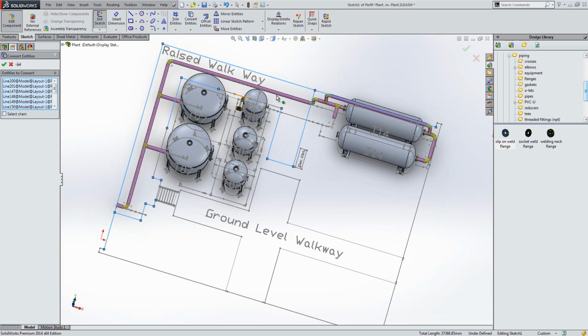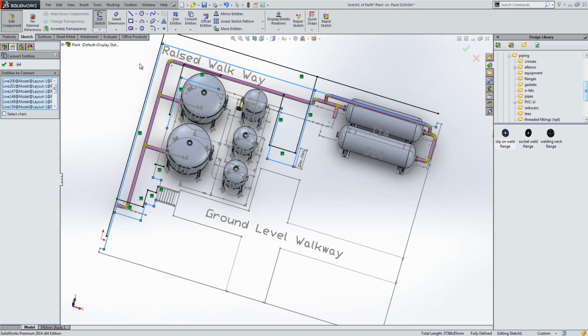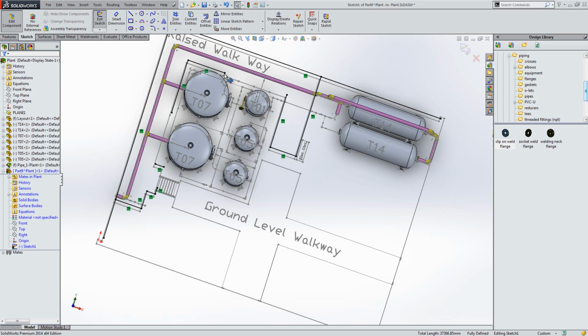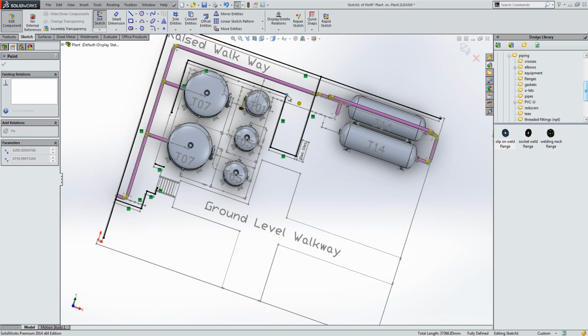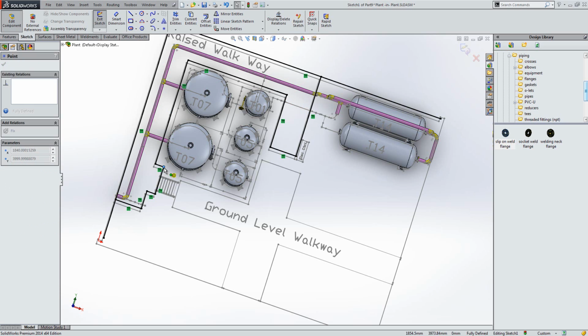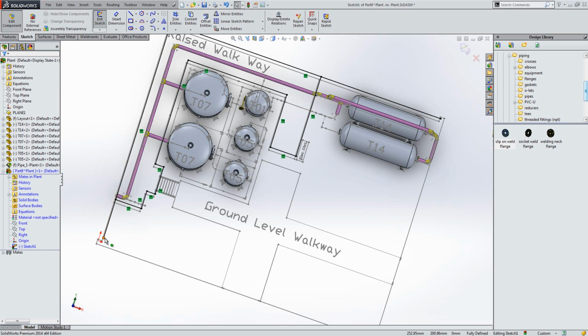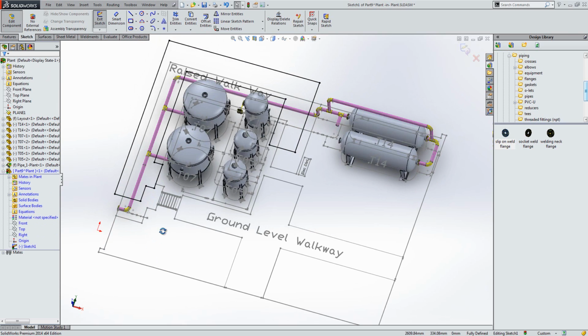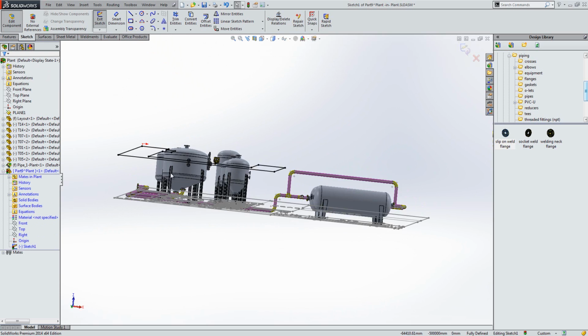You may notice that I've left some gaps. In this case, it's because what I'm going to do is extend the lines that I did select and just join them up. And this means that I end up with single line segments, which makes life a lot easier when we come to look at putting weldments and things along it. I also need to drag back the overextended lines. I could equally use the trim command. So that's my sketch for the outline.